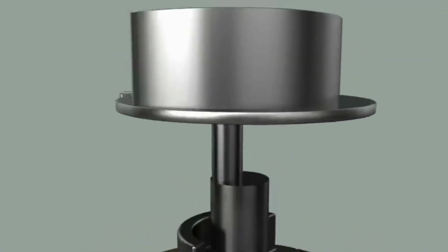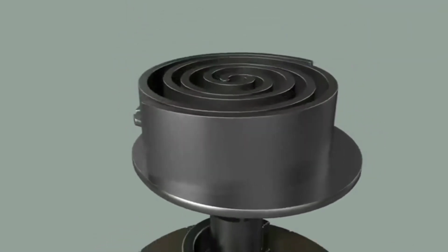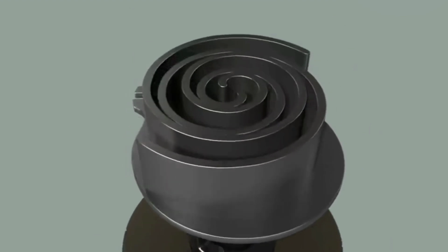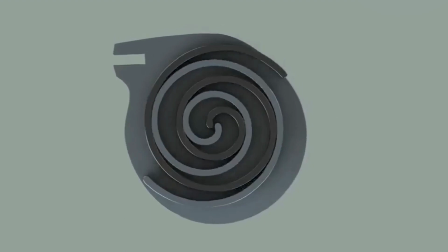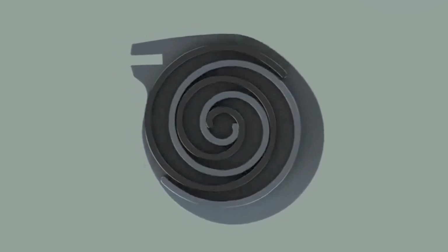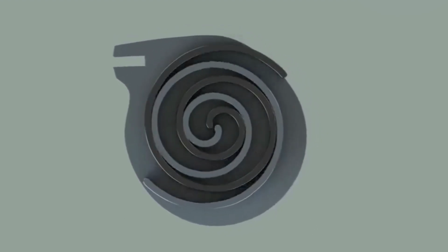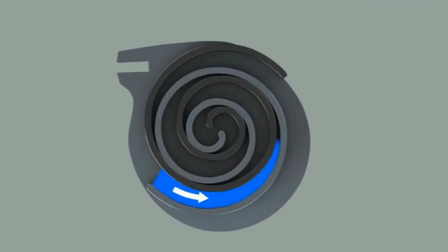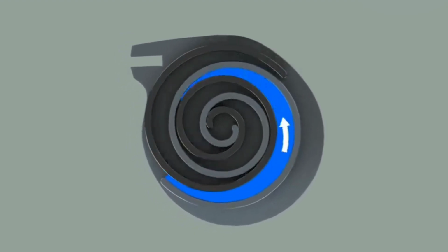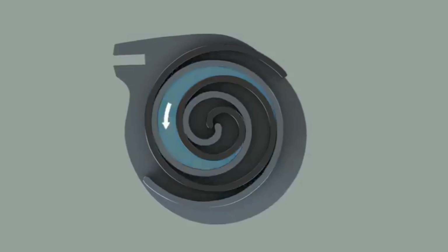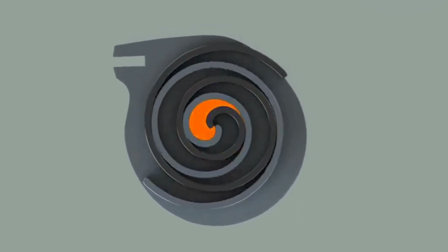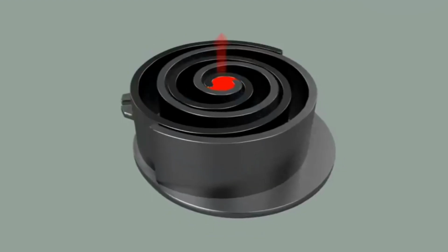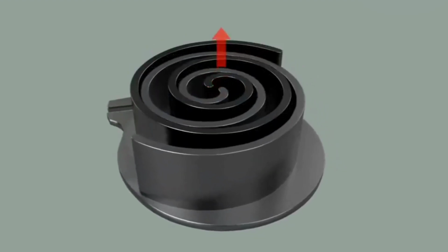However, more air conditioners nowadays use a scroll type of compressor rather than a piston type. In a scroll compressor, there are two scrolls of which one is fixed and the other rolls constantly. As more air coming through the entrance gets inside the scroll, space becomes crowded. As there is less space now, gas becomes more compressed and is discharged from the middle of the scroll in a compressed state.